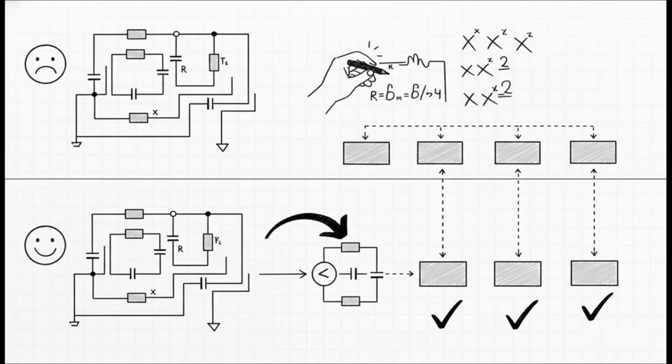The number one reason, it's all about saving time and effort. Imagine you're trying to figure out the perfect load resistor for your circuit. Without Thevenin's, you'd have to do all the complicated math over and over again for every single resistor you wanted to try. But with Thevenin's, you do the hard work just once to find that simple equivalent circuit. After that, testing a new load is just a quick Ohm's law calculation. This saves a massive amount of time, and that's why it's used in everything from designing power grids to building the charger for your phone.